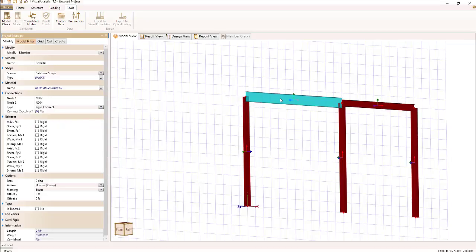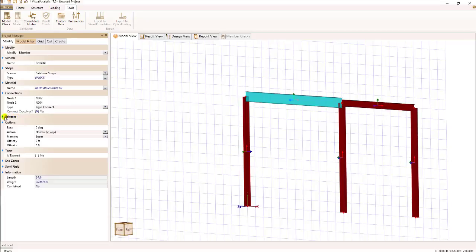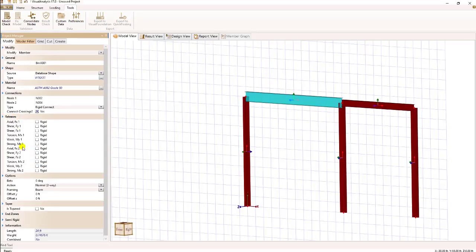If I take this particular beam and select it and expand its releases, and let's suppose I release what's called the strong moment MZ1. Z is the blue axis coming out of the page, and you notice there's a green circle now shown. That is effectively releasing the moment about the z-axis, and we try to view this as more or less a hinge. So the z moment will not be transferred and will be 0 at the end of this member. In addition to the moments, we can also release things like shear forces and the torsional effects at the end.